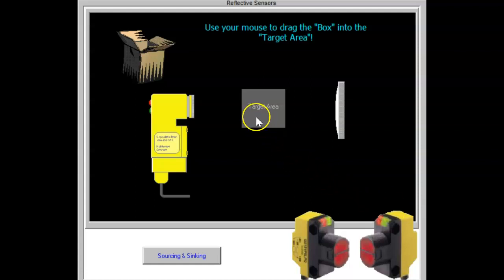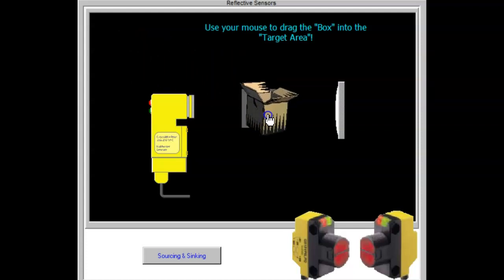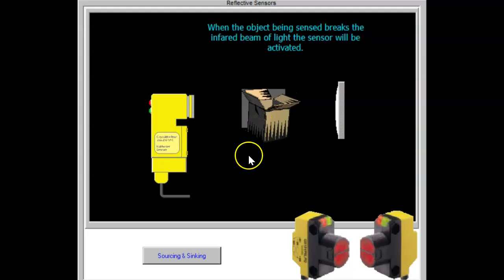Reflective scan sensors have the light source and the photoreceiver built into the same sensor body. Mounting restrictions and limited space sometimes prevent aiming the light source directly at the receiver, so the light beam is reflected either from the target itself or from a permanent reflective target, such as shown above.